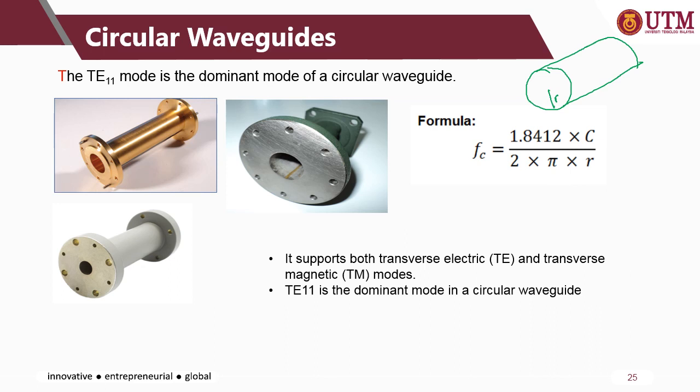It supports both transverse electric TE and transverse magnetic TM modes, and its dominant mode is TE11. For coaxial cable, the dominant mode is TEM mode and the second mode is TE11, but for circular waveguide, the dominant mode is TE11 mode.